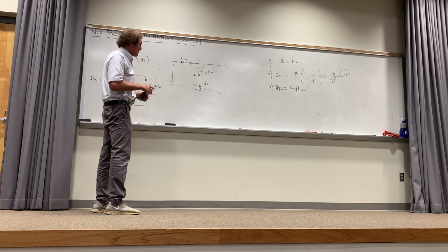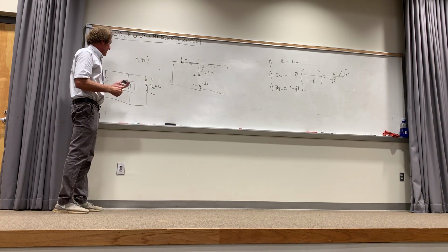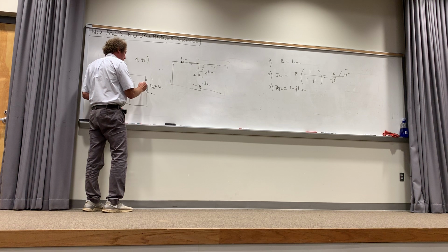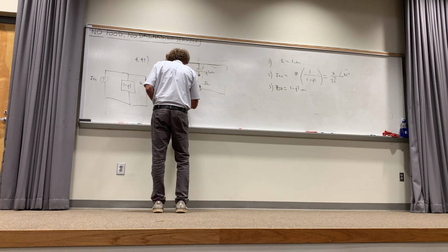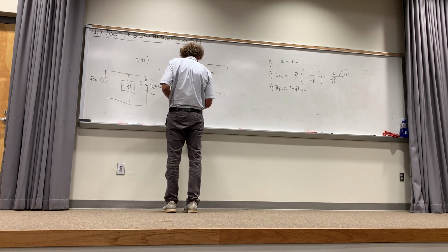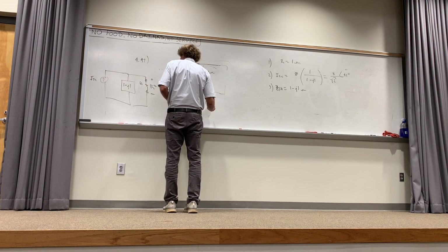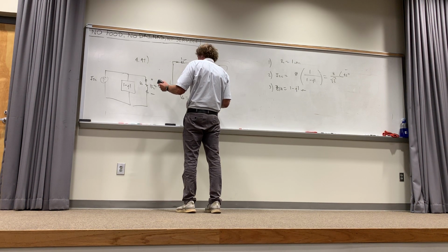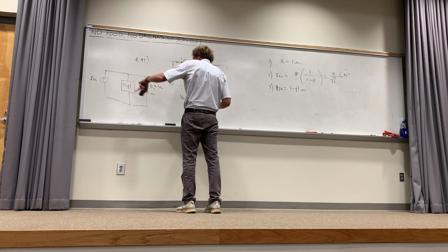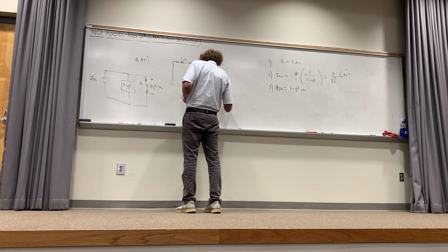All right, now, finally, let's go ahead and get this. If I want this voltage right here, here's what I do. If I want V out, I'm going to take that short circuit current, I short circuit right here. Then I'll do current division, so I'm going to take the opposite, 1 minus j1 over this plus this, or 2 minus j1.